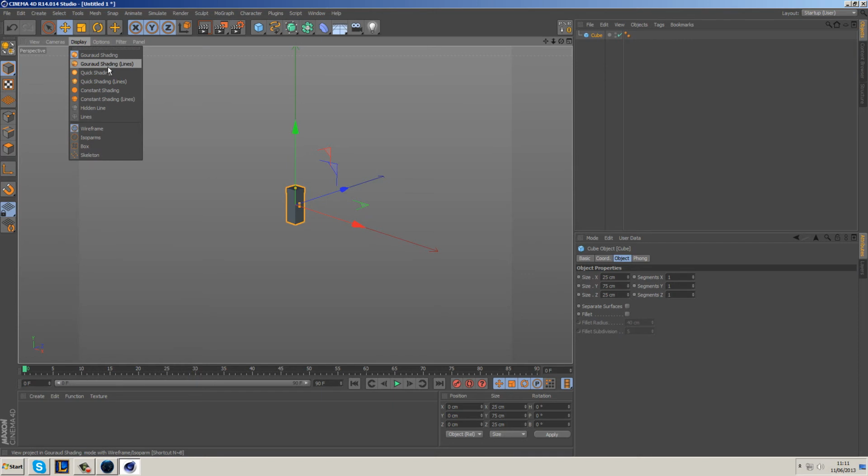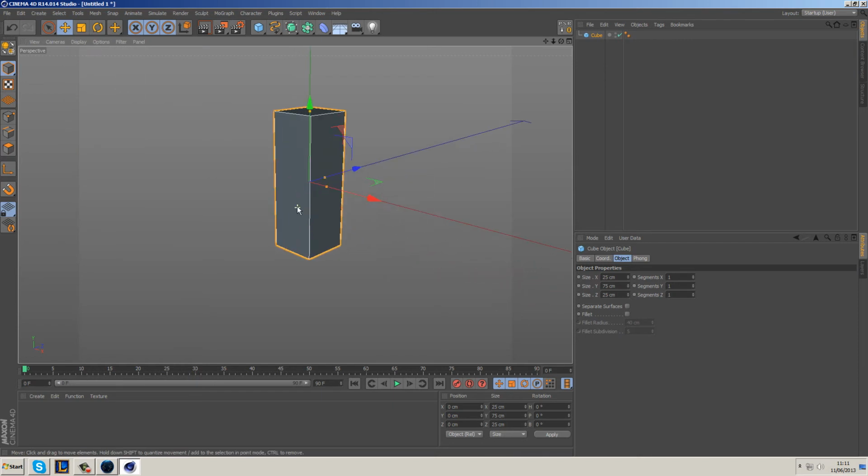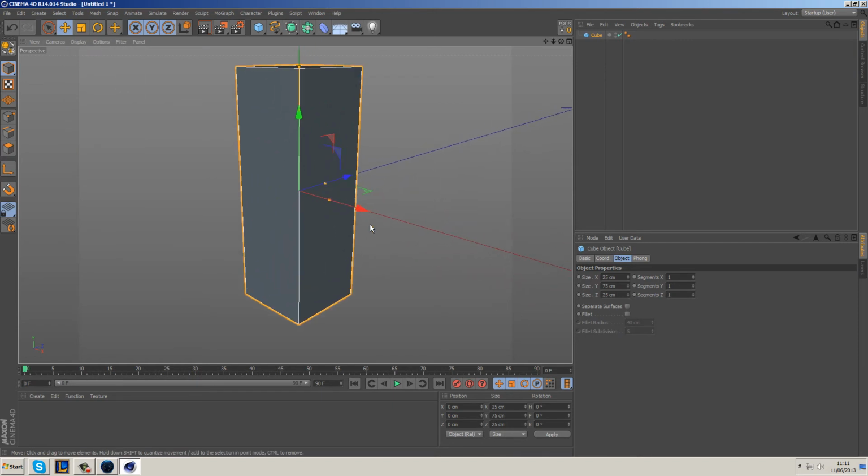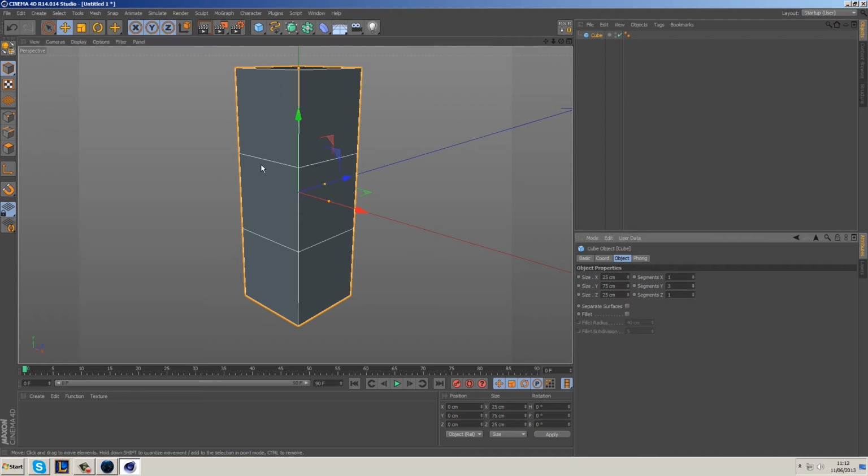We're going to put on the ground shading line so we can see, because the lines that we need are important. We actually need 3 segments. Well, actually, let me rephrase that. We need 3 lines, but it's going to require 4 segments. If you see over here in the Y segments, if we put this to 3, we're actually going to get 2 segments, which isn't what we need. We need 3, so we have to up the segments on the Y to 4, which gives us these 3 lines.